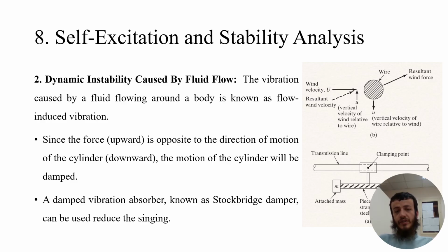How can we reduce this vibration? Just by designing a vibration absorber damper known as the Stockbridge damper, which has two masses and two ends. One is this end, and this end. We place it where the cable experiences a large vibration.